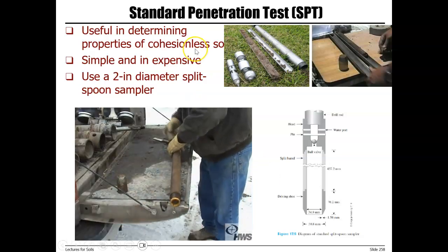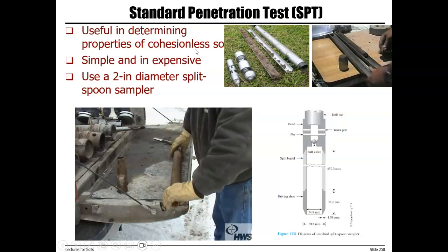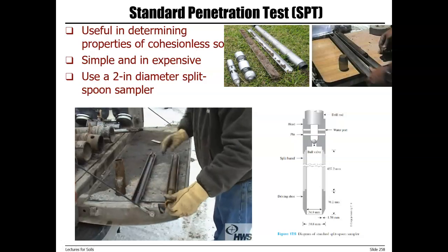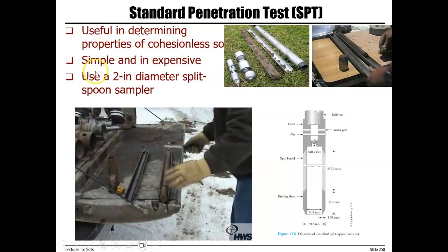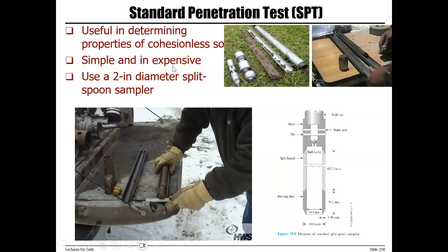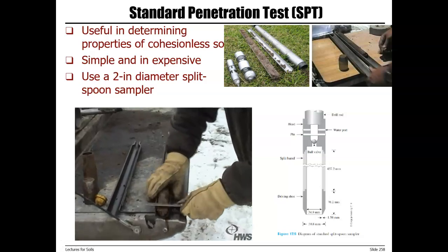SPT, as I said, is the most widely performed field test for soil evaluation. It's simple, inexpensive, and it provides a soil sample.